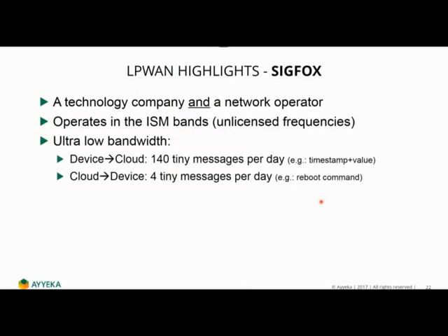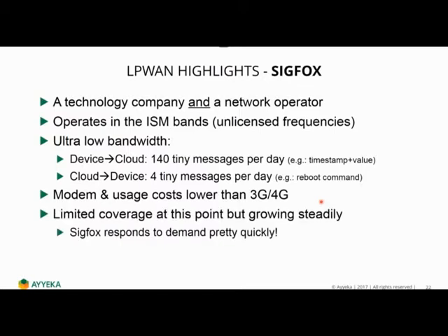Sigfox is an ultra low bandwidth technology, or ultra narrow band, sometimes it's called. A device can send to the cloud 100 tiny messages per day. When I say tiny message, I mean something like a timestamp and a value. The cloud can send a device 4 tiny messages per day, so that's really nothing. Something on the order of a reboot command, but nothing else really. The good news is that the modem costs are much lower compared to 3G and 4G.